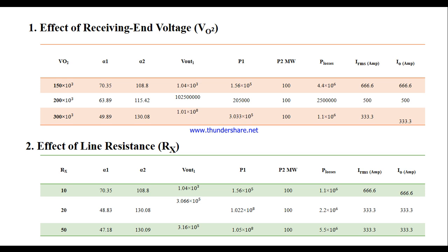We notice that when we increase the line resistance Rx, our closed loop control system reduced the DC current. This was not just to stabilize power but also to maintain a safe extinction angle, which is known as gamma, at the inverter. By doing so, the system avoids inverter commutation failure. It proves that our control design ensures stability under harsh grid conditions.